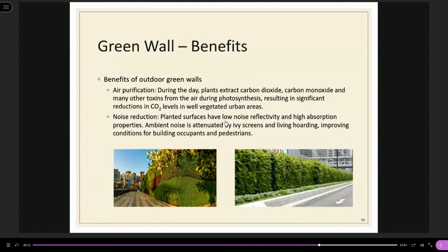Okay, so many barriers in Hong Kong are actually very reflective. So instead of absorbing the sound, if they are using the reflective hoarding, then the sound will be reflected to the other side of the road. So we are not solving the problem. We are just directing the noise to another direction. So we better use absorption material.